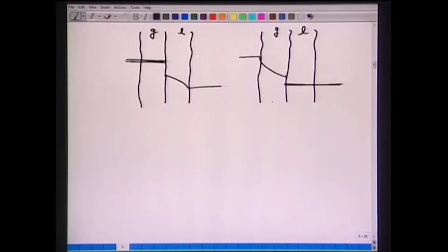Now, let's sum up what we have done. We have equilibrium given by thermodynamics. So given the mole fraction X, we have Y. Given the partial pressure in the liquid phase, we have the gas phase concentration in the other phase. So this is thermodynamics. And now we can mark our operating points. We can mark all four concentrations in the bulk phase, in the gas phase, and what the driving force is, YA minus YI or YA minus Y star, etc. So these points we can now mark based on our discussions in the previous lectures.